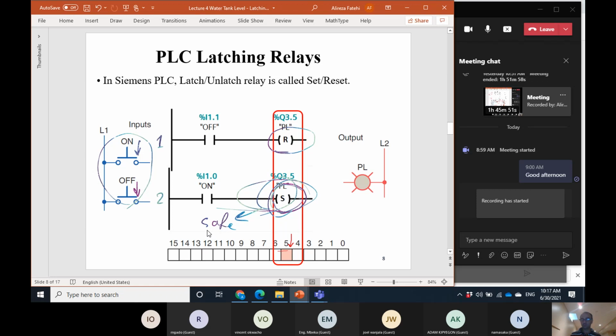For example, for the motor, generally the safe mode is to be off. For the valves, it depends on the valve. For most valves, the safe mode is that they should be closed. But for safety valves, those used for discharging high pressure gas from boilers, for example, the safe mode is opening the valve.